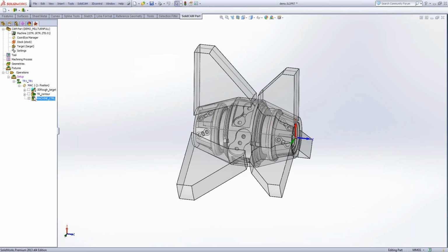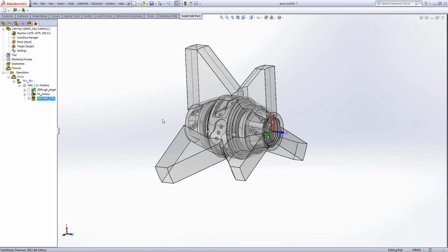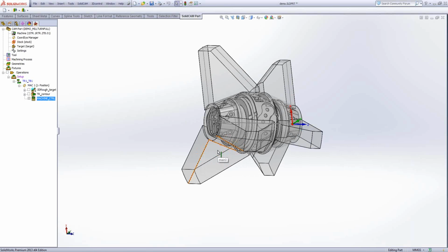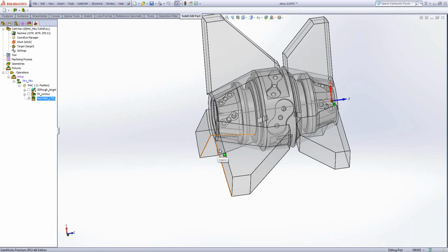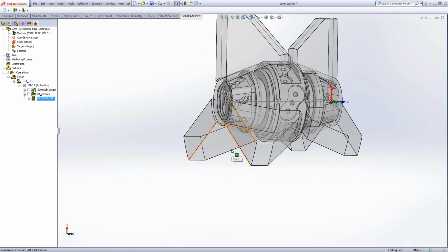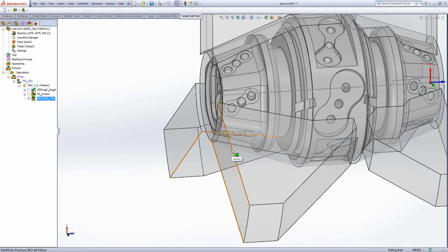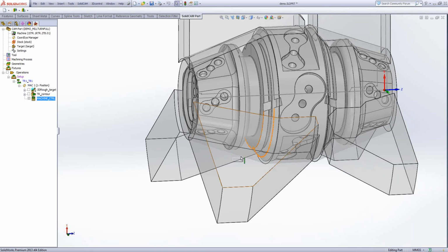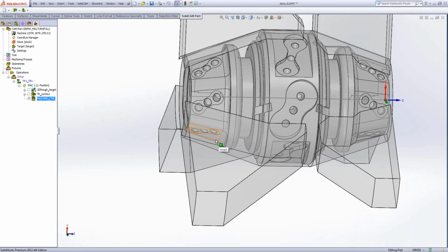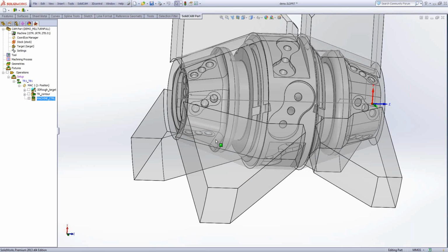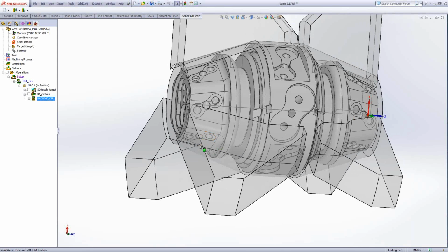Now I want to show you another great option that we have now, working with a rotary turret with an angle tool. That means if you have a holder, angle head can be fixed, or you can set up the angle.